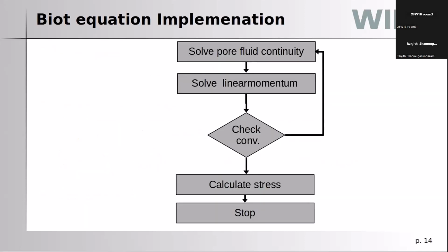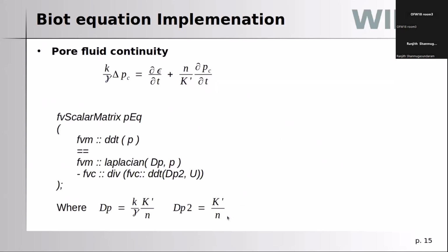Initially, the approach is that we solve the pore fluid continuity equation, and then the linear momentum equation. Finally, we check for convergence, and after that we calculate the stress for the solution. In OpenFOAM, we can simply implement this continuity equation with this approach.